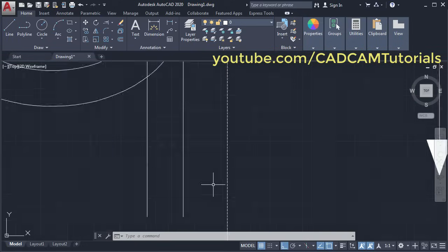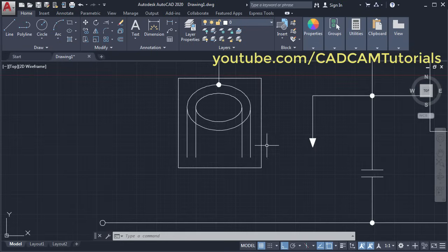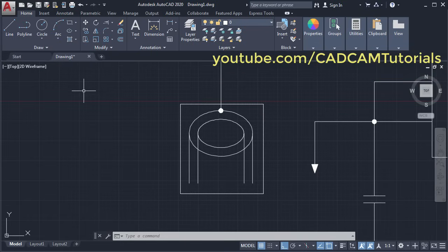Now it is converted to hidden, but the gap between lines is very small. To increase the gap, type LTS for line type scale, enter, then increase the scale factor. Suppose I will make it 5, enter. Still I will have to increase it, press enter, I will make it 15, enter, zoom minus.